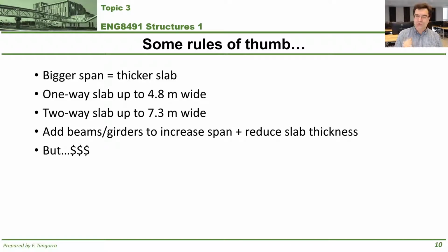The only thing is though, when you start doing stuff like this, you increase the price of the structure, okay? Because with reinforced concrete, you pay for the shaping of the structure, the forming, you pay for the reinforcing, and you pay for the human labor time associated with that. Okay? The expensive part in reinforced concrete structures is typically considered the forming, okay? Because it has to be, it's usually custom, usually, okay?